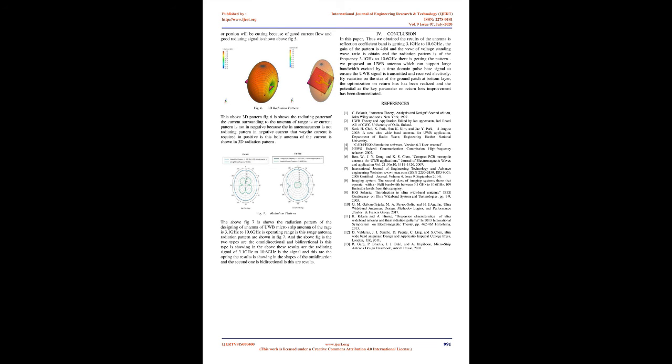By varying the size of the ground patch at the bottom layer, the optimization of return loss has been realized, and its potential as the key parameter for return loss improvement has been demonstrated.